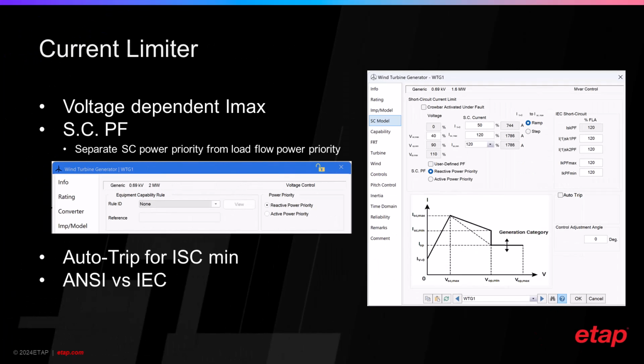Now, as you see in the FRT curve, there is a dot in the curve that's crossing the origin in both positive and negative sequence curves. So what does that mean? If you look at the WECC model or dynamic models typically out there, in this case, there's a timer. In the WECC second generation model, there's a timer.